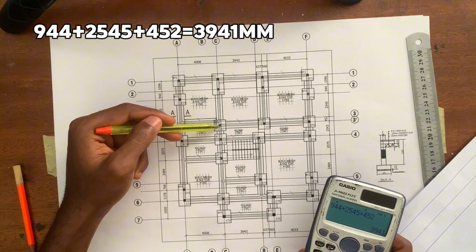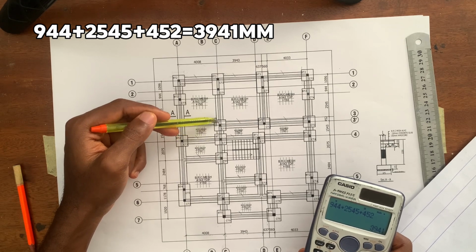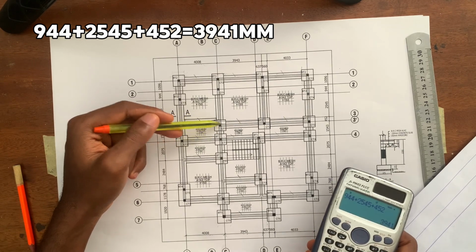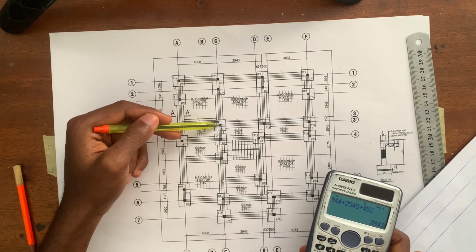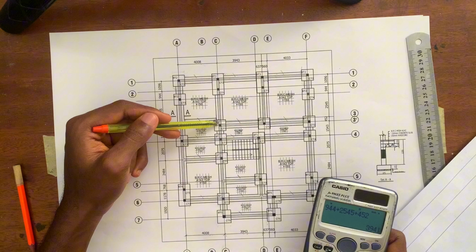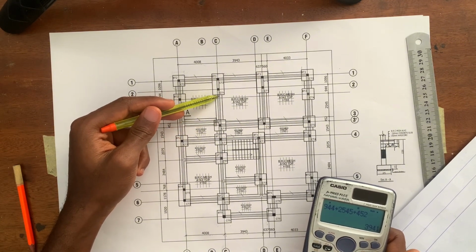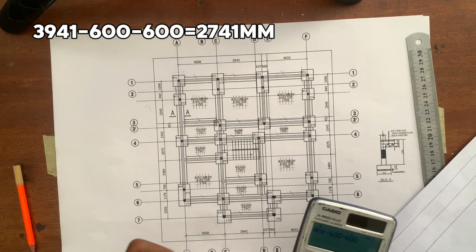So we're going to be minusing half of the length, or the width rather, any one you choose, because they are equal, 1200 by 1200. If we divide 1200 by 2, we're going to get 600. So we're going to minus 600 from here and 600 from here. So 3941 minus 600 minus 600, we're going to have 2741.